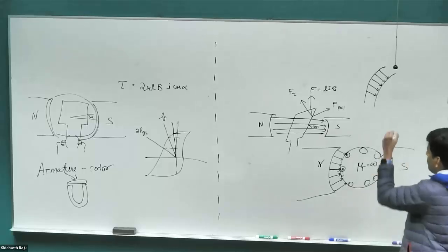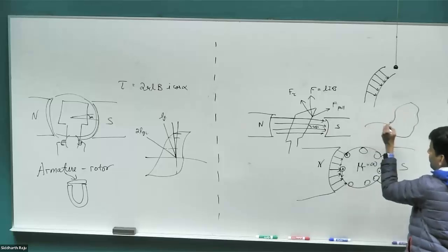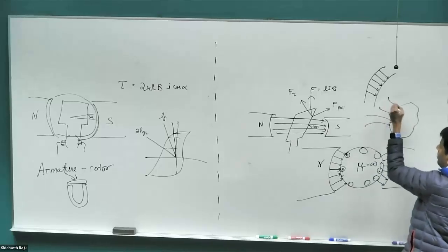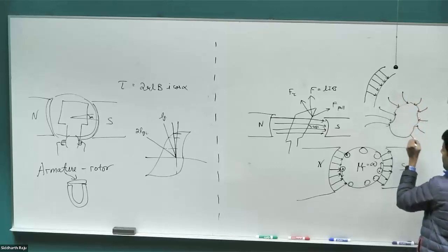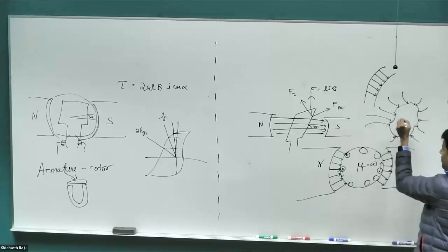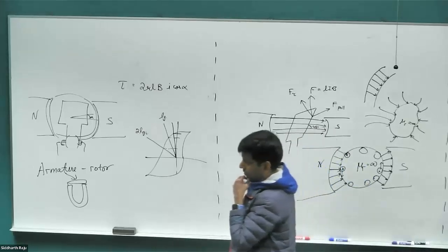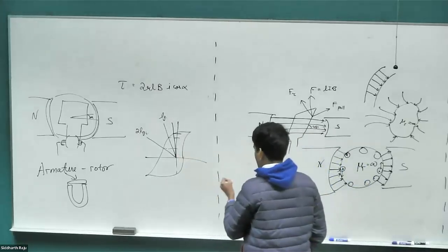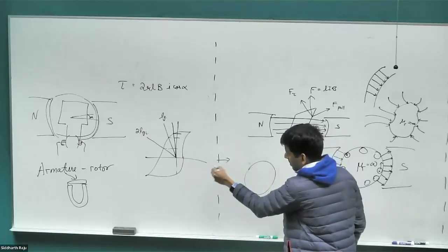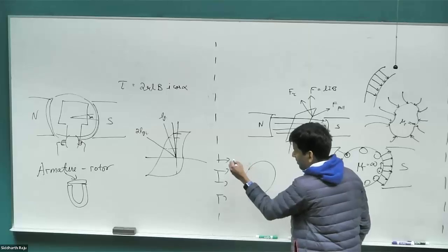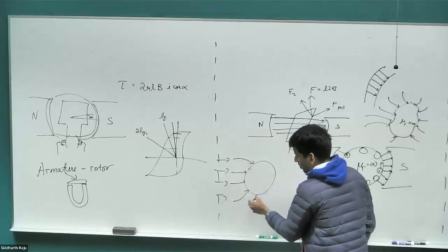And this happens with any kind of surface that you have. If you have an odd looking surface like this, and you have some external magnetic field, all of those magnetic field lines will terminate perpendicular to the iron core. Doesn't matter what kind of structure you have, assuming the permeability is very large. This is similar to when you did the case for electrostatic analysis in your electromagnetic theory course. If you had a spherical conductor and you had some external electric field coming from, say, a parallel plate or something, once it approaches the sphere, they would all terminate perpendicular to the sphere.